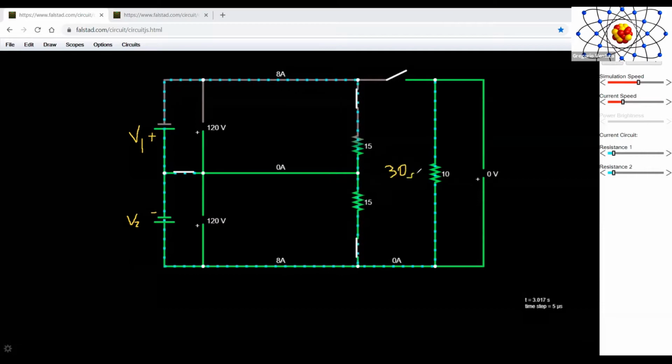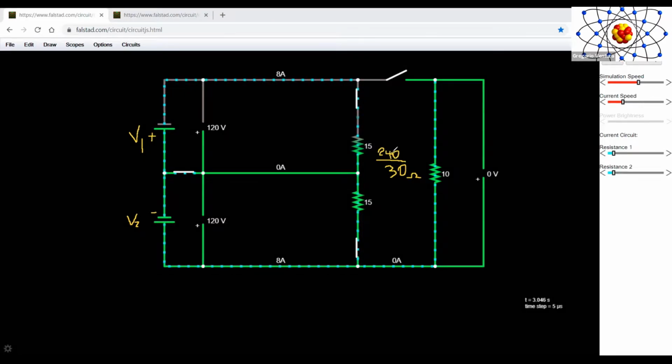if we divide the 240 volts that is being applied to those two resistors together that are connected in series, indeed, we are going to have, as indicated by this current source, 8 amps. And we are going to have 8 amps on both wires. So we have an input and a return path, which is the output, right?